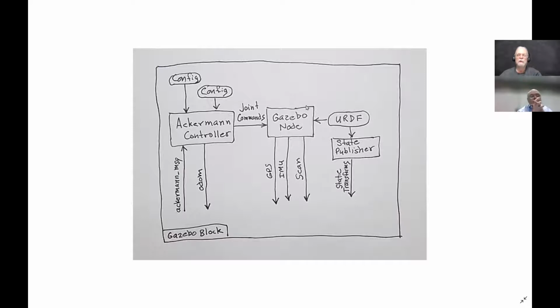And then if you want simulated sensors, here you can drop a simulated GPS into the URDF file. And there you say, I want to add a GPS. It's located here on the vehicle. Here are the parameters as far as its range and the angle it can scan and various other things. So that will create a GPS. I haven't looked to see what that's putting out, if it's a standard navsat fix, a navsat velocity, a navsat status, or if it just puts out latitude and longitude. If it is just putting out the basic stuff, then I could write a node here to convert that into the standard navsat fix type messages.